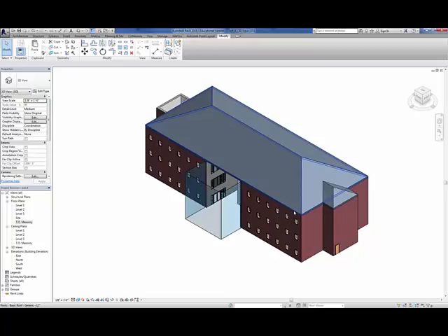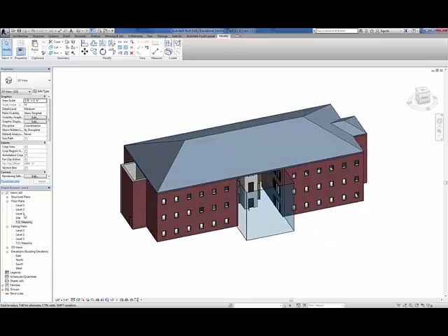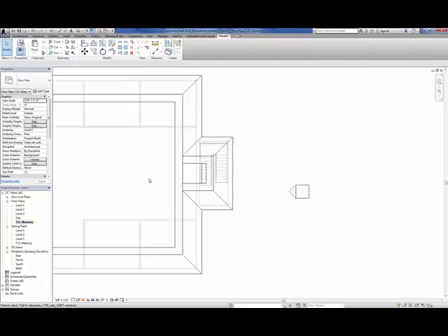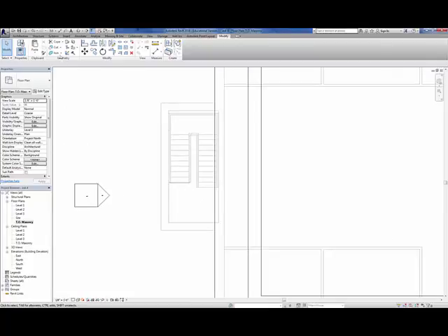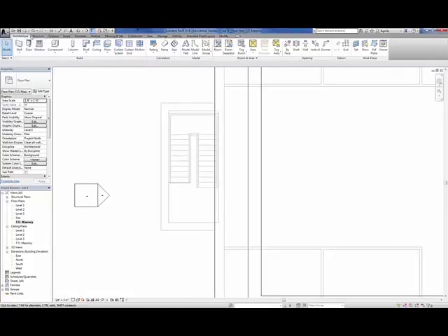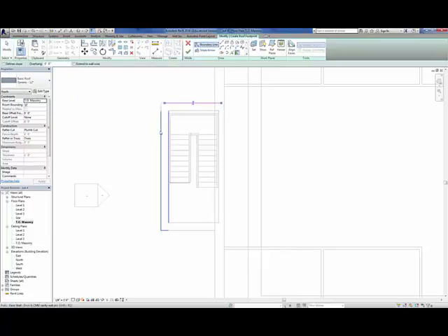Once we've done that, this roof extends over and clips in and joins that roof. Now we can do the exact same steps on the other side. So let's go back into top of masonry. Move over to the other side. And we're going to go back to architecture, roof by footprint. So first thing, when we do roof by footprint, remember we need to turn define slope on first. Let's select these guys. Turn define slope back off.